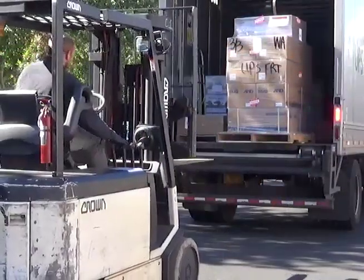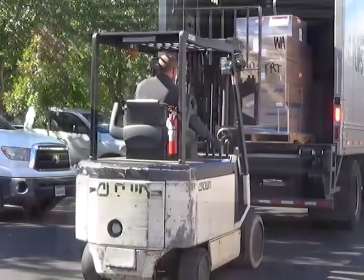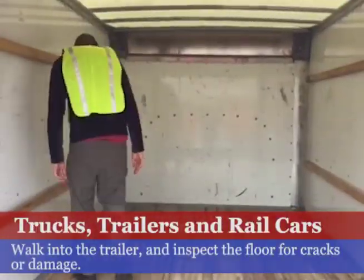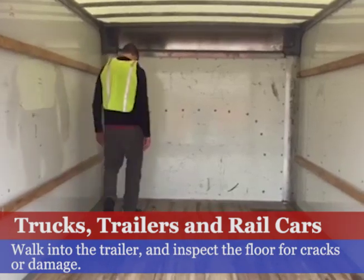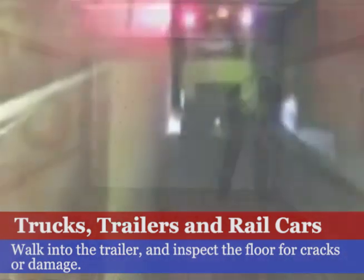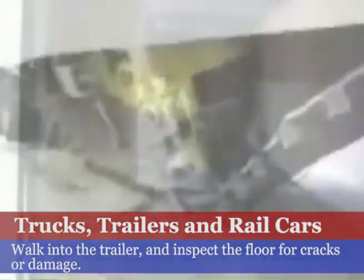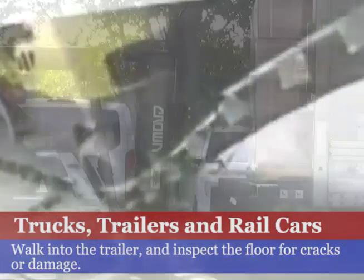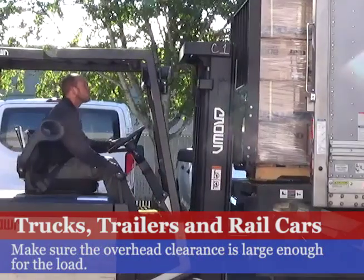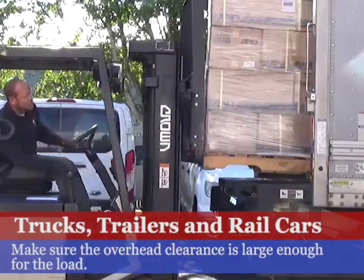As a forklift operator, you may have to load or unload trucks, trailers, or rail cars. Before driving into a trailer, walk in, and inspect the interior. Check the floor for cracks or damage. Forklifts are heavy, and they can crash right through a weak support structure. Check the overhead clearance. Make sure the opening is large enough for the load being transferred.